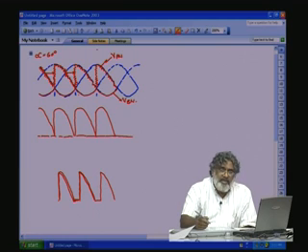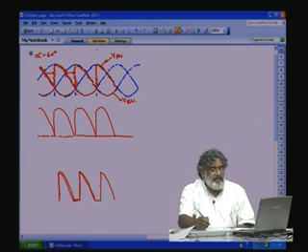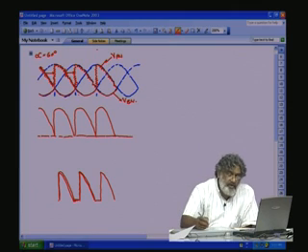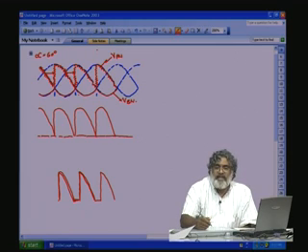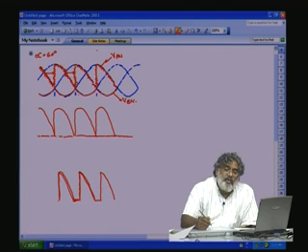So apart from the finite turn on and turn off time, because of the circuit inductance, the leakage inductance due to the wiring or power circuit bus structure or due to the transformer, there is a delay in the turn on and turn off process. So this can create a decrease in the output DC voltage due to this commutation overlap. What I mean is, turn on and turn off are not instantaneous. There is a period the commutation process goes through. That is called the commutation overlap. Due to that, there can be a reduction in the output voltage. So we will study about that in the next class.